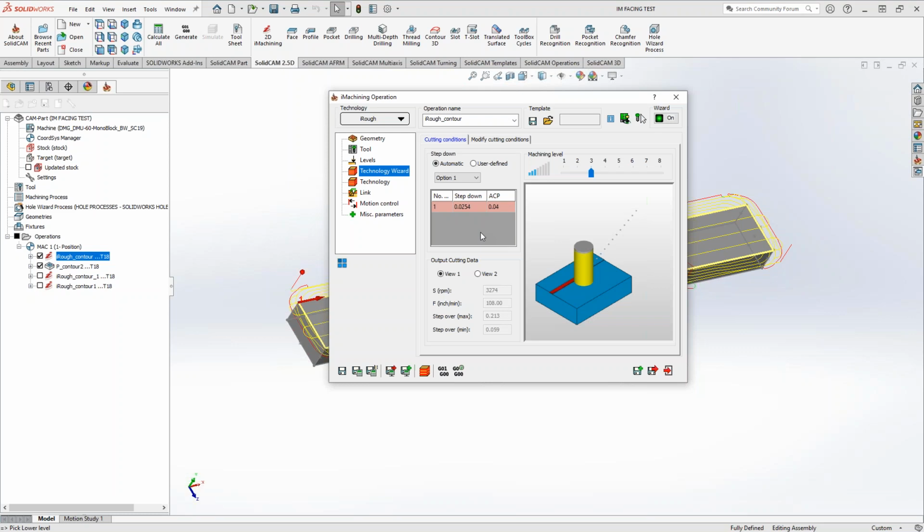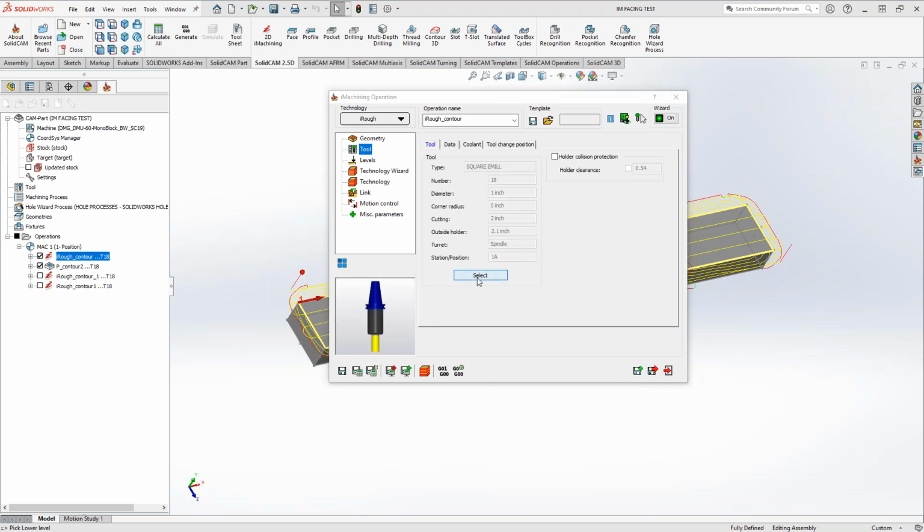If we wanted to, we could switch to a different tool, maybe optimize the use of the tool a little bit more. But in this case, again, because it's so shallow, we really wouldn't be using iMachining anyway. It's overall just going to be inefficient. Unless you had a really small diameter tool, really small flute, and then maybe you're optimizing the use of this tiny tool. But well, let's try out of curiosity.